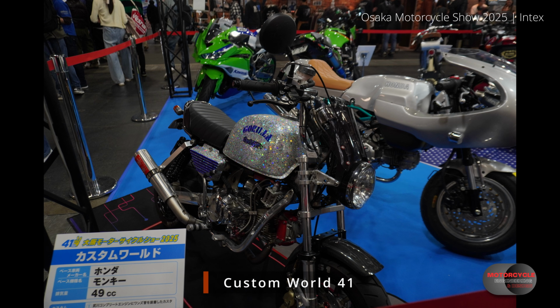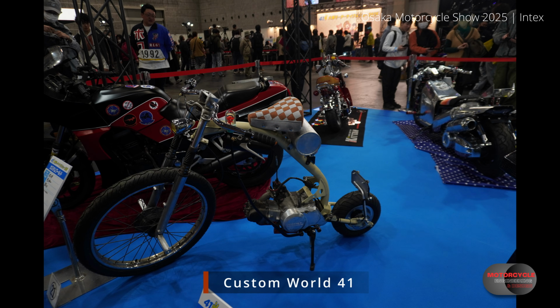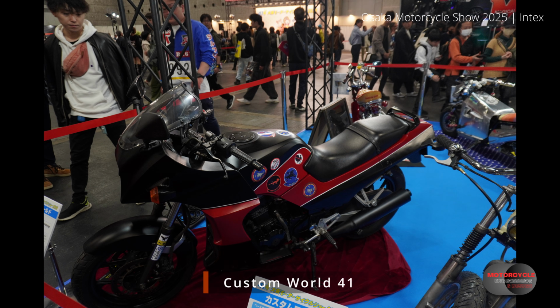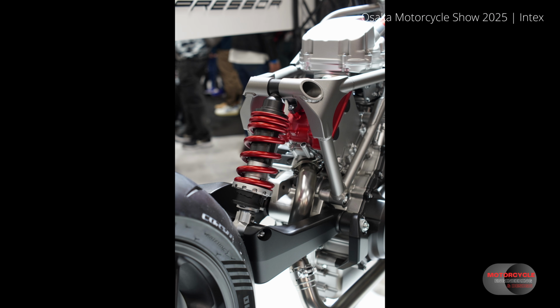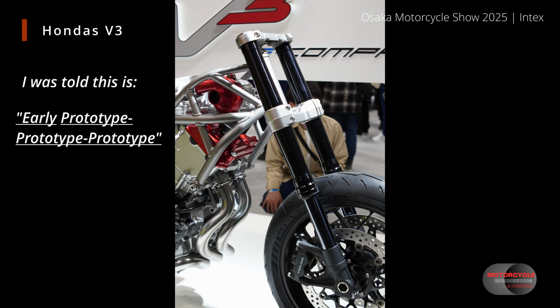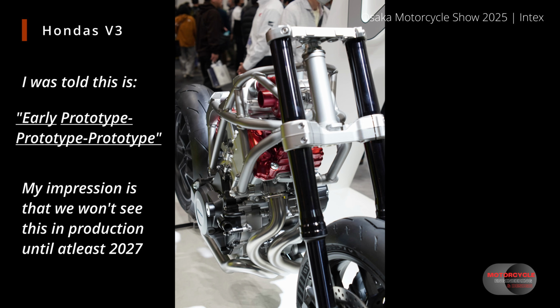When the exhaust gases are flowing down the pipe, they're flowing extremely fast, just for short bursts because of the pulsing action of the valve opening and closing. What this results in is, as it reaches an expansion in the diameter of that pipe, we'll have a pressure drop. And that pressure drop is going to pulse back to the exhaust valve, helping to pull out any remaining fumes and even potentially pulling it into a vacuum condition. Ideally, we're aiming for a greater differential pressure between the inlet and the chamber.